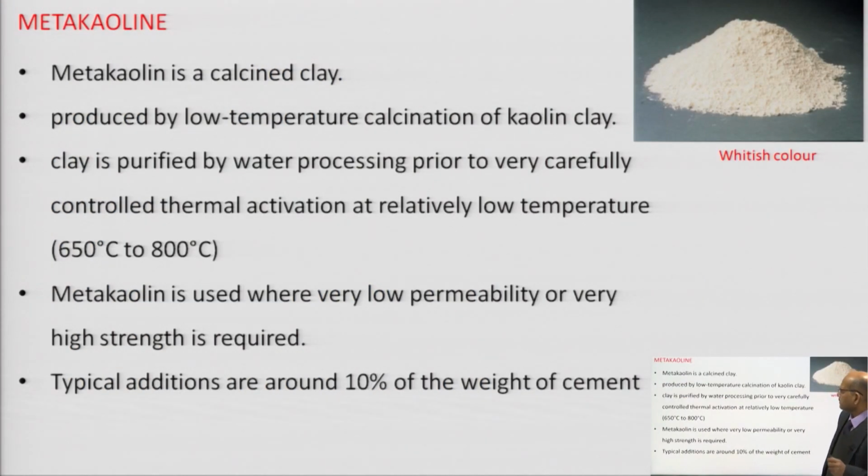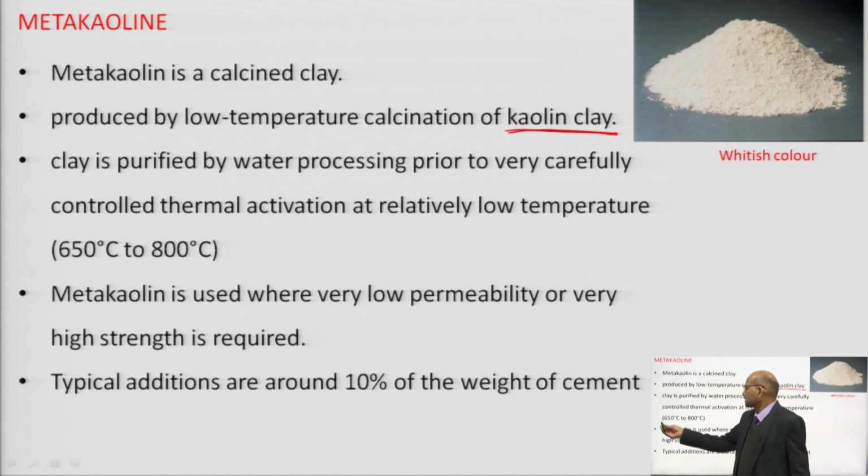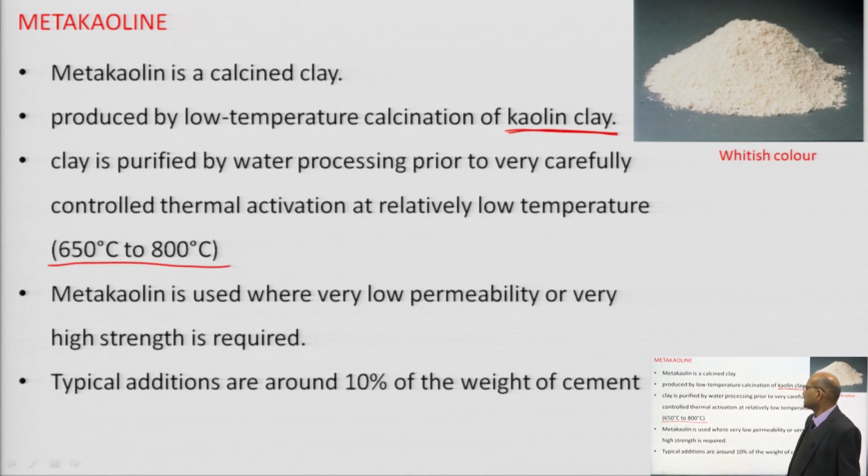Okay. So, I will discuss briefly about metakaolin. Metakaolin is a calcined clay. This metakaolin is produced by low temperature calcination of kaolin clay. So, you have to take the kaolin clay and go with a low temperature, working up to a temperature of 650 to 800 degrees centigrade.